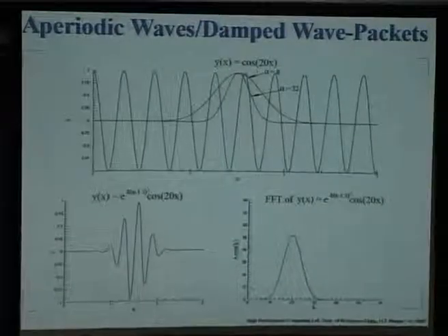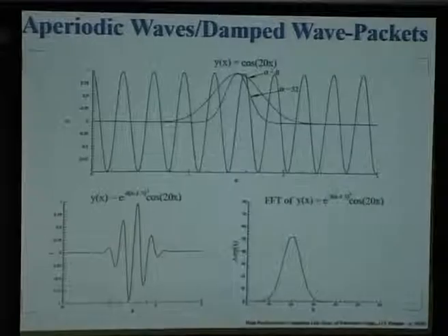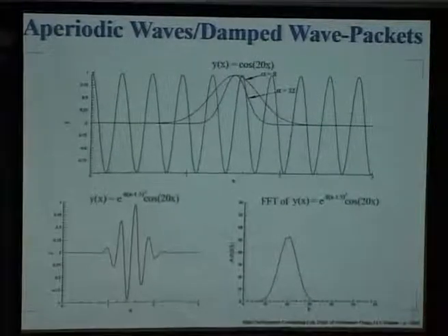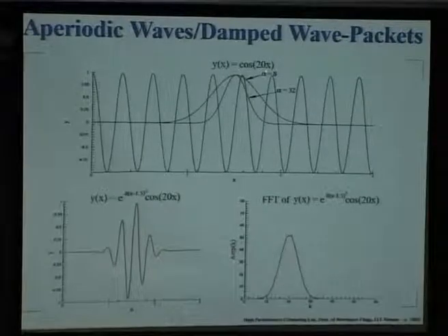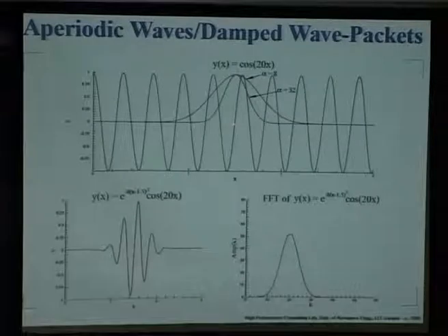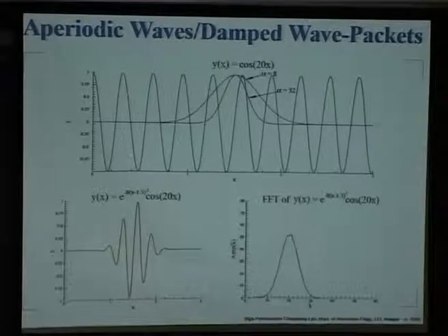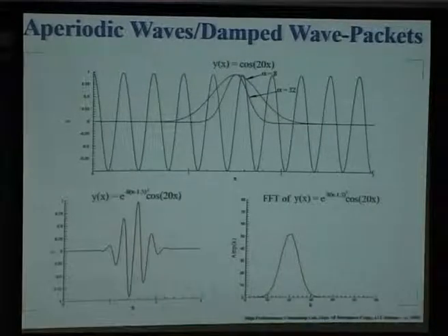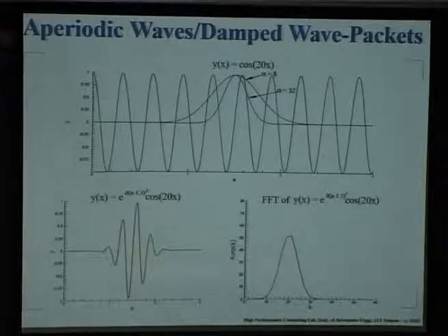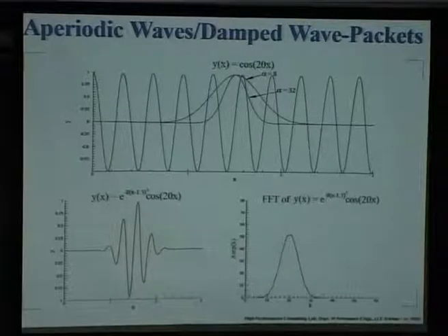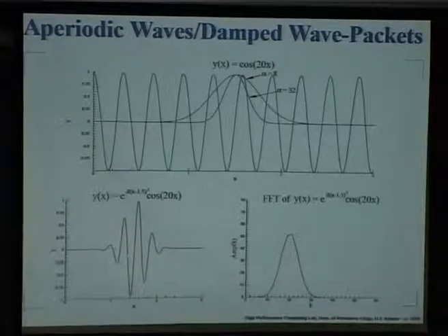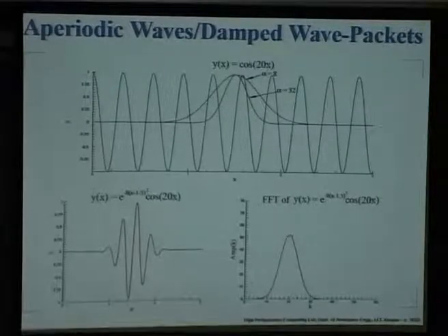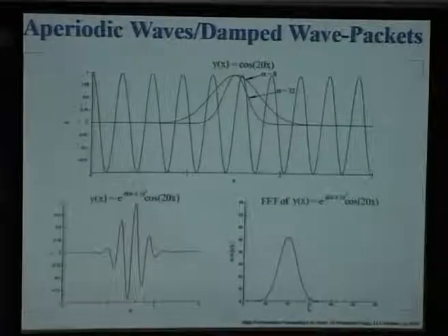So that is one way of communication, where we can send monochromatic waves or send a kind of packet. But there is another way signals are quite often transmitted: when the signal is embedded in an amplitude envelope, which renders it aperiodic. We have the basic signal cos 20x, and we modulate its amplitude by this Gaussian function. The signal information you are carrying still corresponds to 20x, but its amplitude decays, so you have almost zero amplitude outside this single packet.